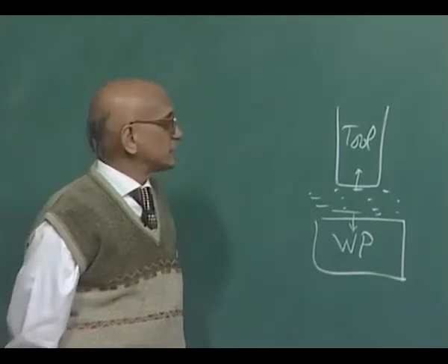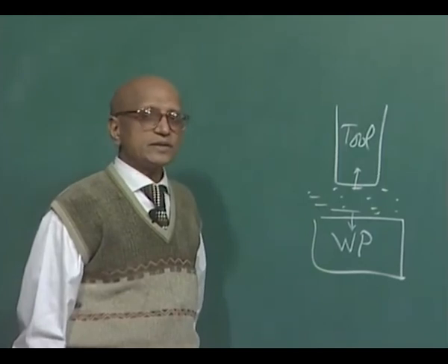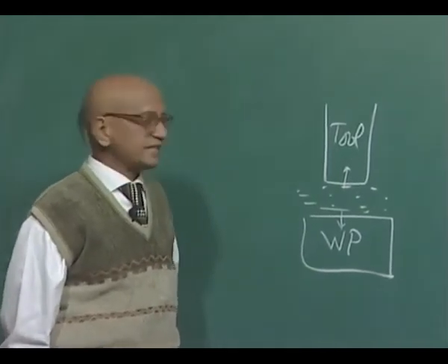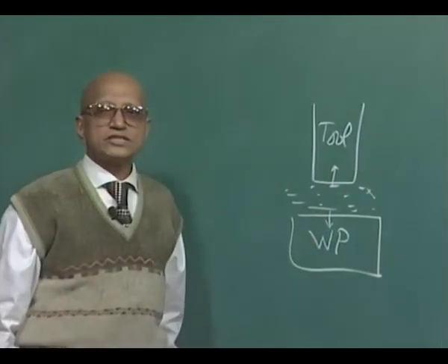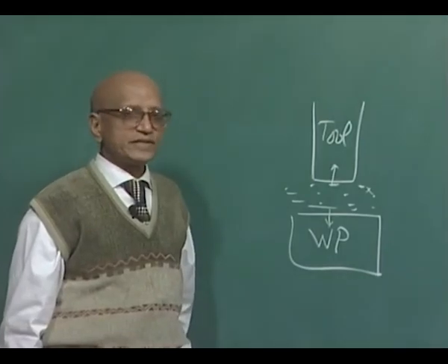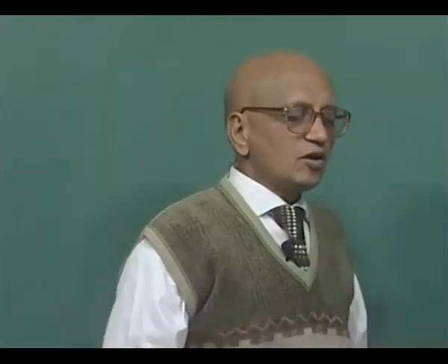is negligible. The thermal conductivity of the tool is very high. However, for simplification of the problem, we are considering it negligible. Also, we are neglecting here the losses due to the radiation, because the temperature developed is not very high. So, we can easily neglect the heat loss due to the radiation.